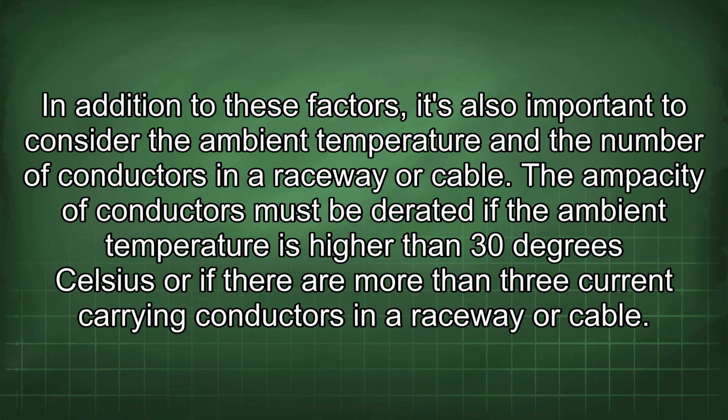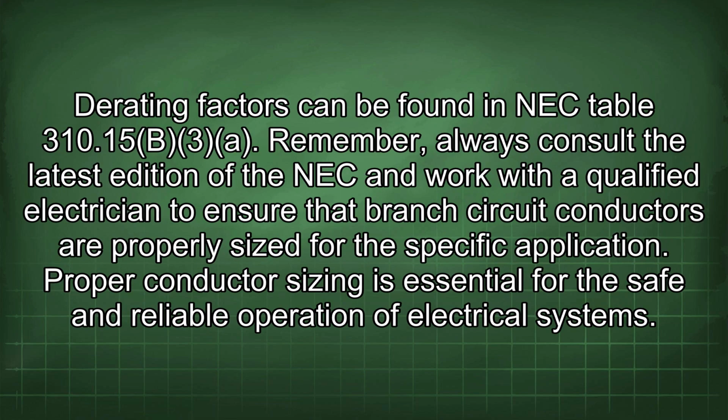The ampacity of conductors must be derated if the ambient temperature is higher than 30 degrees Celsius or if there are more than 3 current-carrying conductors in a raceway or cable. Derating factors can be found in NEC Table 310.15(B)(3). Remember, always consult the latest edition of the NEC and work with a qualified electrician to ensure that branch circuit conductors are properly sized for the specific application. Proper conductor sizing is essential for the safe and reliable operation of electrical systems.